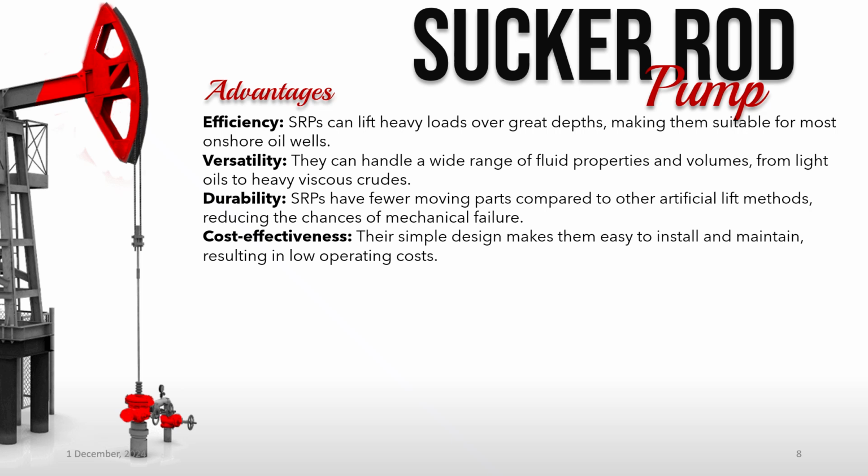Versatility. These pumps can handle a wide range of fluid properties and volumes, from light crude oils to heavy, viscous crudes, and even fluids with some gas or solids content. SRPs demonstrate considerable adaptability, making them a robust solution for diverse well conditions. Durability. Compared to many other artificial lift methods, sucker rod pumps have a relatively simple design with fewer moving parts. This inherent simplicity contributes to their durability, reducing the likelihood of mechanical failure and extending their operational lifespan.